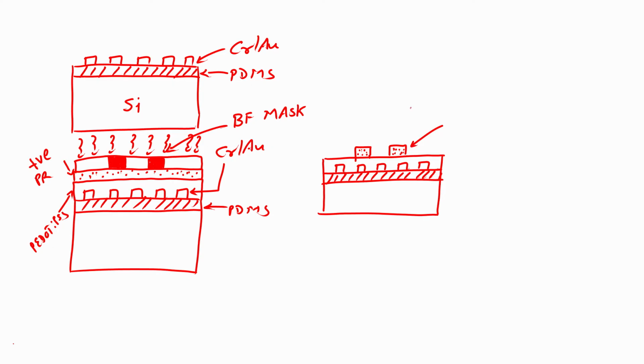So, you have here positive photoresist, this one is your PEDOT:PSS, which we have spin coated, you here have chrome gold, then you have PDMS, then you have silicon.